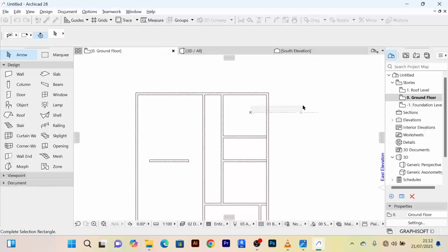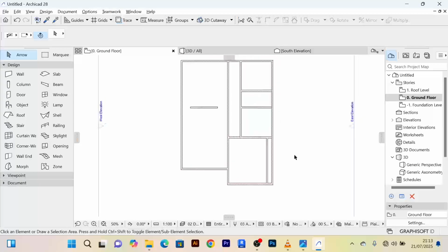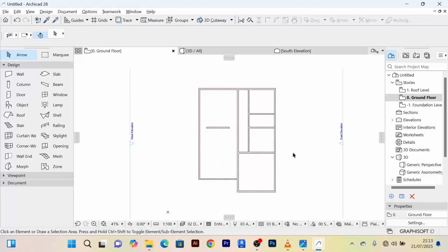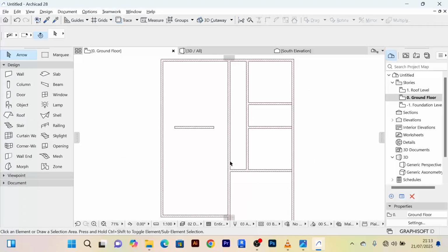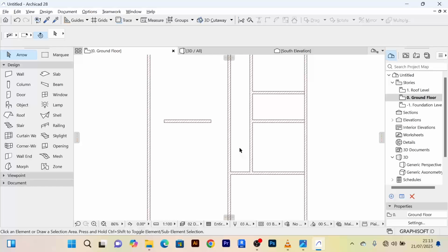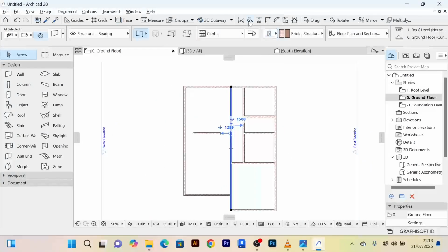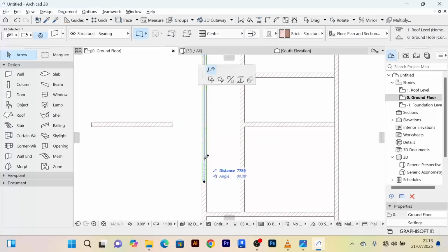Then this is bedroom 1, and then this is another bedroom, and this is another bedroom. So I can delete this one off. Just like that, we have created those parts very well. Now for this one here, we can also create an opening here for people to access this side. You click on this wall, click on that wall, you come to the split. You can split around here. I want to preserve that side.